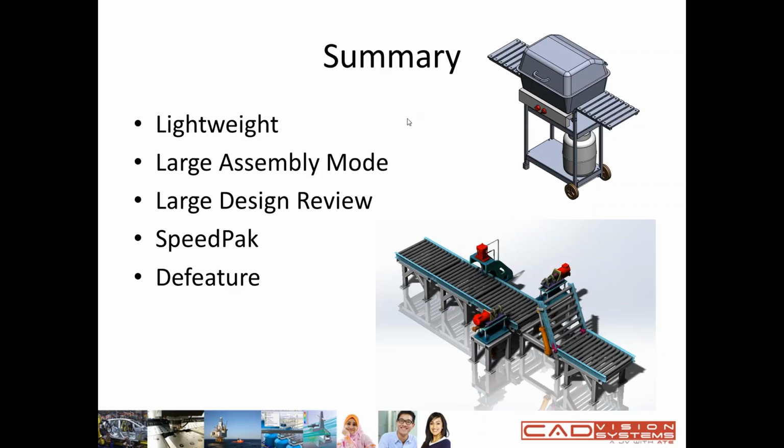Large assembly mode involves a set of options based on an assembly with a minimum number of components. You can set the number of components, and when you reach a certain amount, when you open the file you go straight into large assembly mode. About large design review: it lets you open a large assembly really quickly, while still retaining the capabilities that are useful when conducting a design review for an assembly.